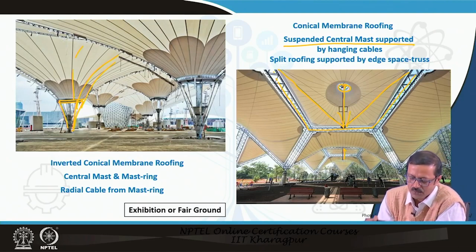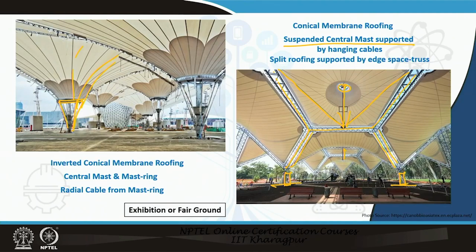In a very beautiful way, from the central mast the cables are attached. So finally, who is taking the load to the ground? It is this particular part of the truss member which finally supports the load and grounds it, this is the column. So it's a real wonderful combination of a three-dimensional linear kind of truss, a triangular kind of space frame.